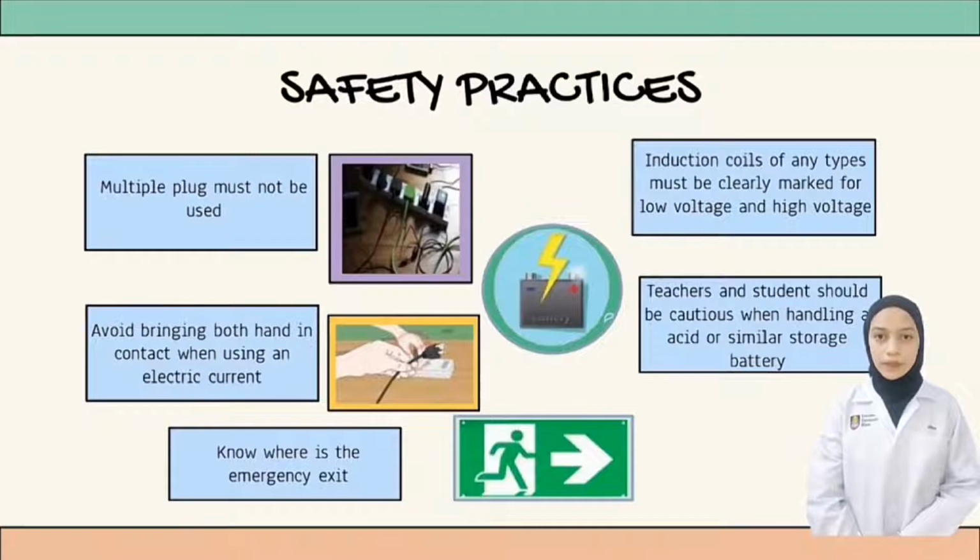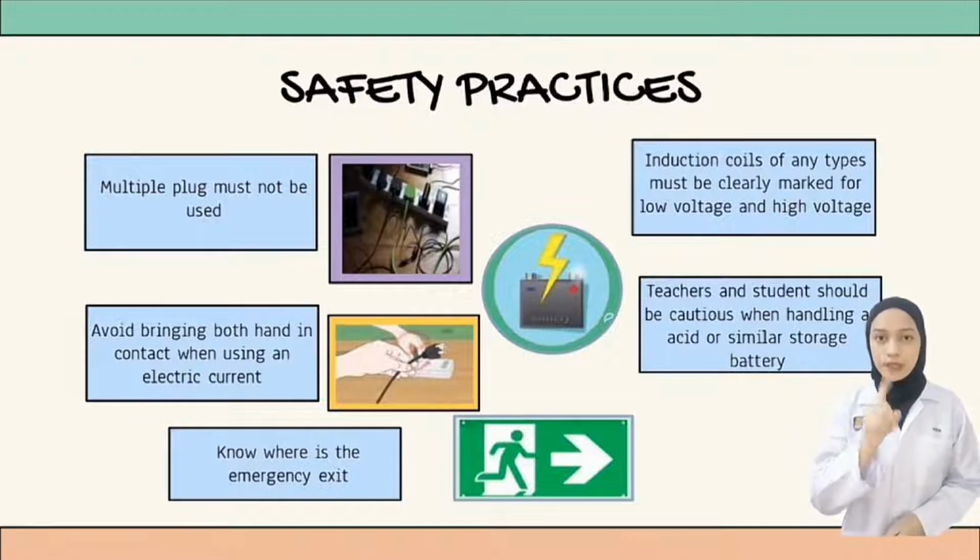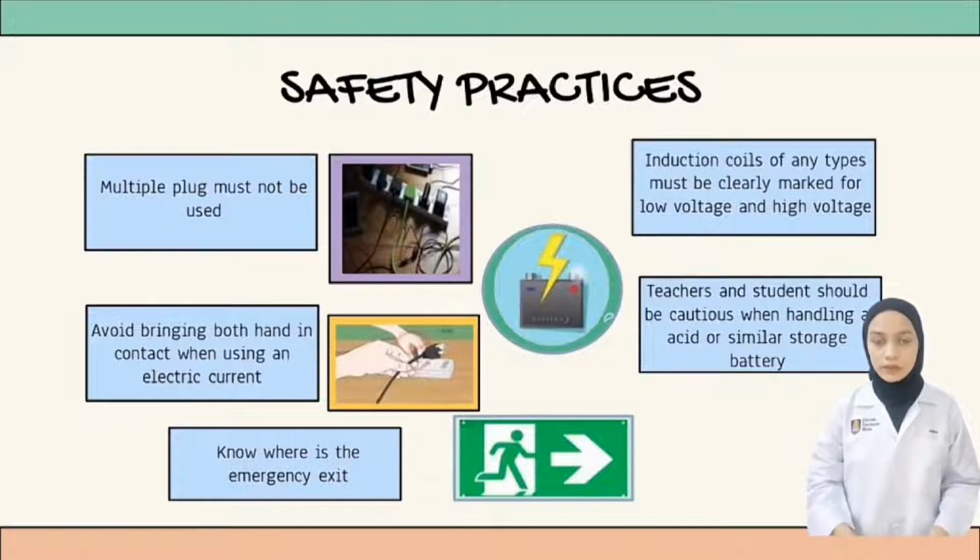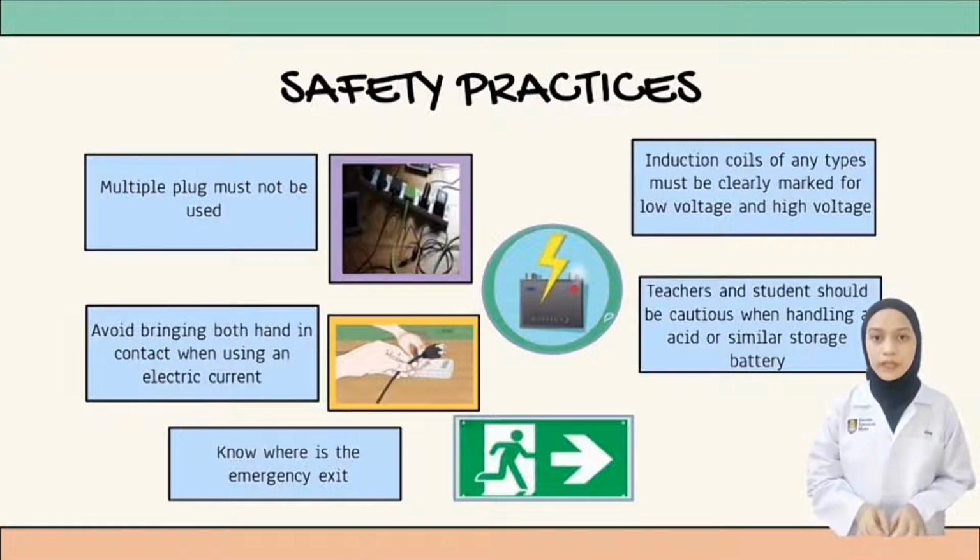Before we go further into our topic, we need to know the safety practices during the laboratory session. Firstly, multiple plugs shall not be used. Multiple plugs can cause an electric shock. Overloading an extension lead by plugging in appliances together will exceed the maximum current rating for the extension lead. This could cause the plug in the socket to overheat and possibly cause a fire.